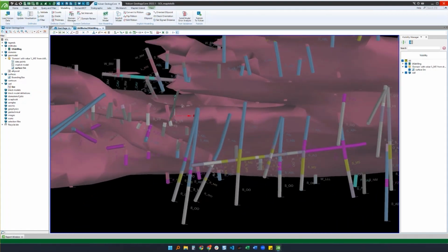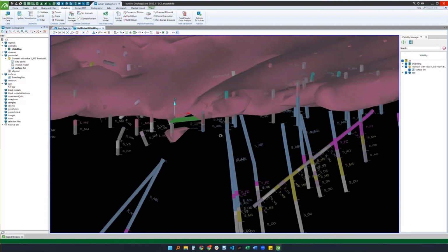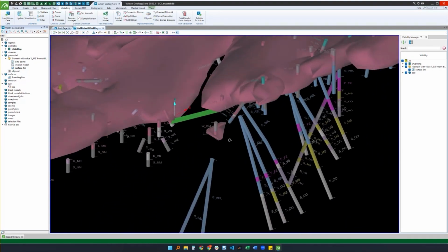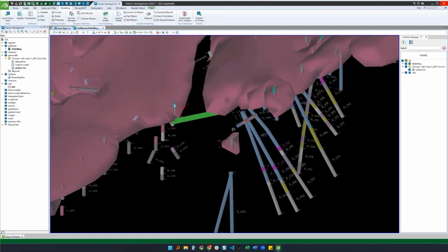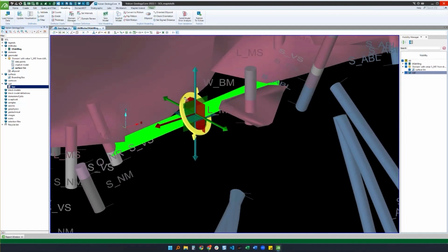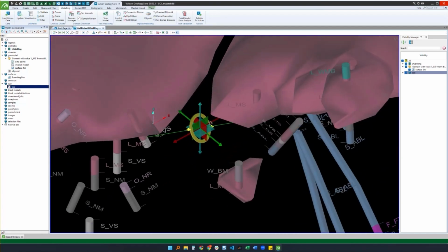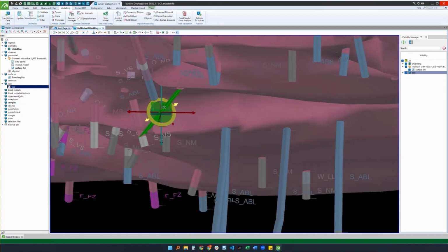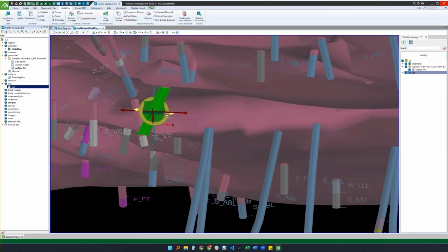Now this is kind of the underneath of my surface, so I want to make sure that the colored side is on the outside of the surface and the uncolored side is on the inside. So I'm going to select that, I'm going to use edit ribbon, that's going to bring up my manipulators, and then I can just use my middle mouse button to spin the ribbon around to the orientation that I want. So we still want to tweak that a little bit.